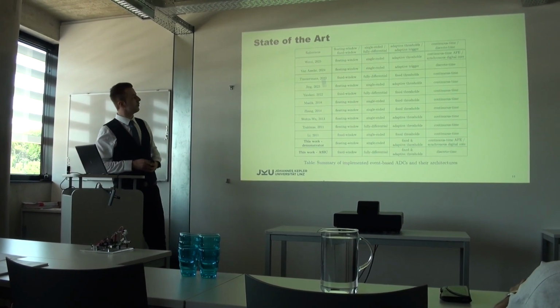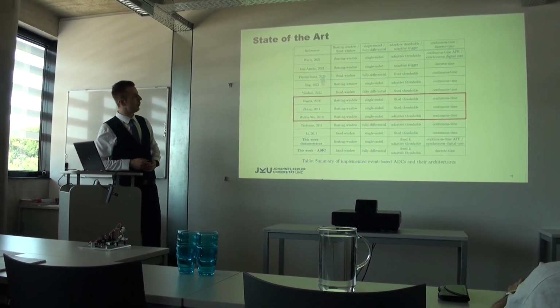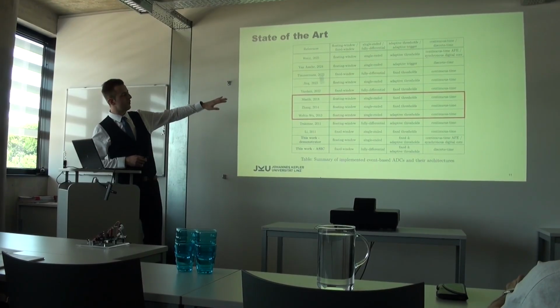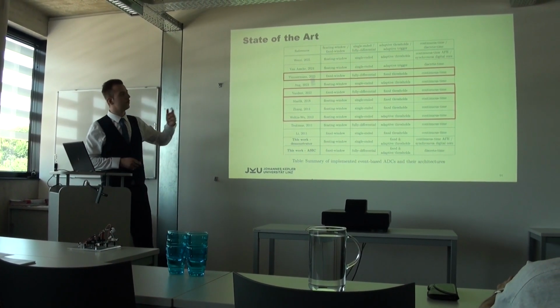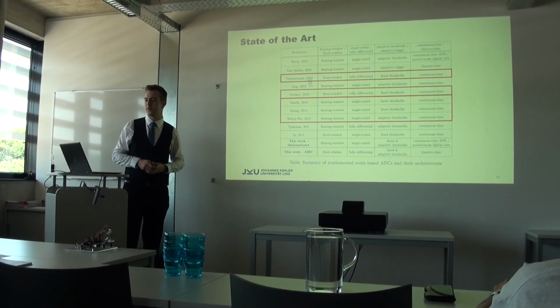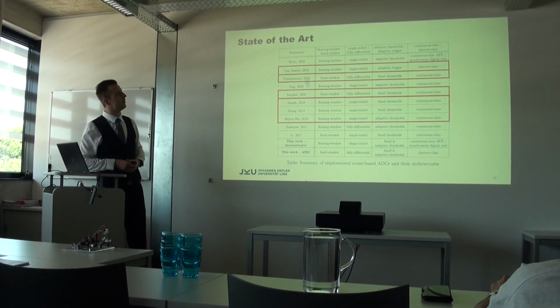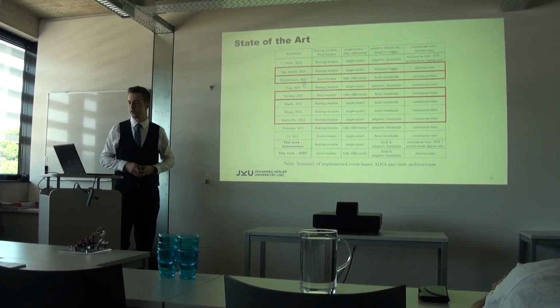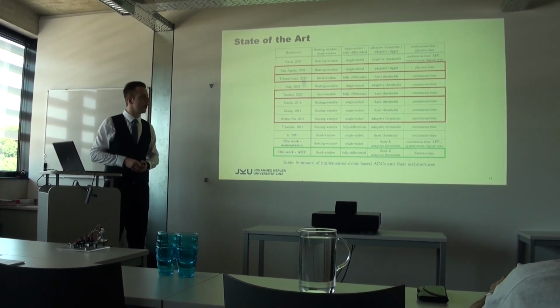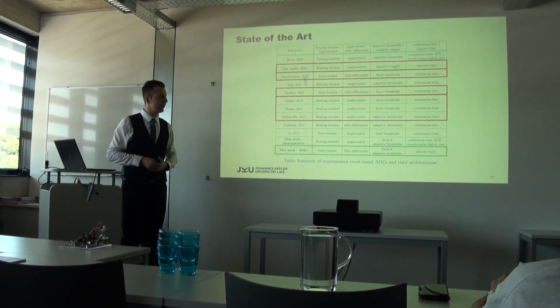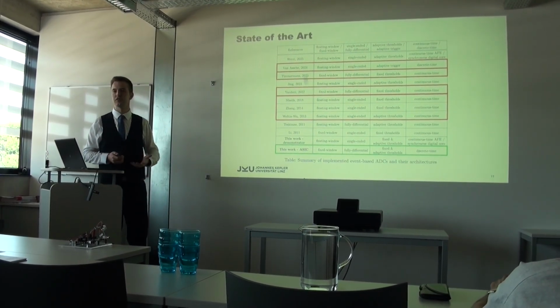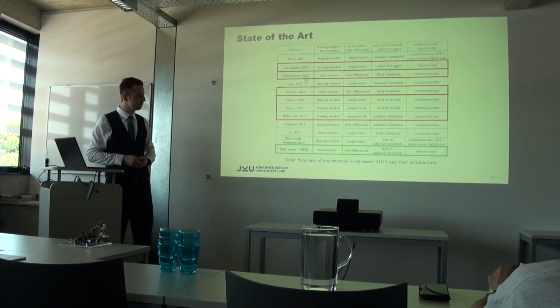And just to have some state of the art right now, a lot of people are doing floating window compared with single-ended, or fixed window with fully differential outputs. And there is only one event-based ADC with a discrete time analog front end. So we want to do now a combination of everything: a fixed window, fully differential, adaptive thresholds, and a discrete time event-based ADC.